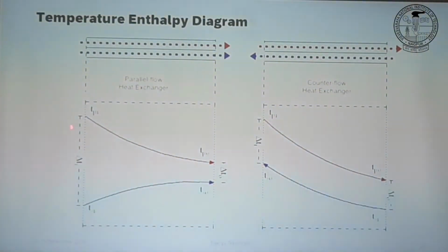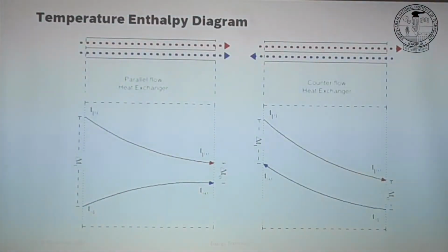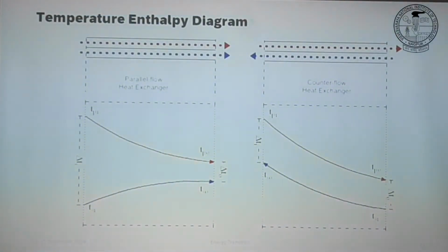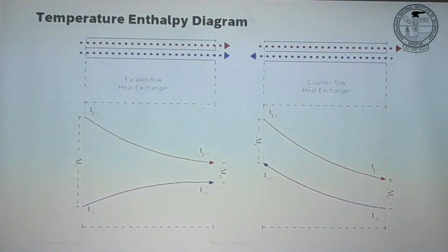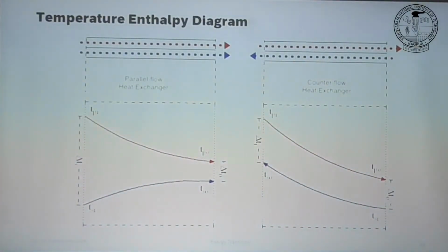There are many other cases. Sometimes you have a temperature sensitive case. Very good, that's what I wanted to explain now. So imagine you have a hot side flue gas, but on the cold side we don't have air. We have natural gas, and natural gas has a tendency to crack at a certain temperature, 650, 670. So if you have natural gas in your pipes, you don't want to have heat sensitive material. So there you want to have cold